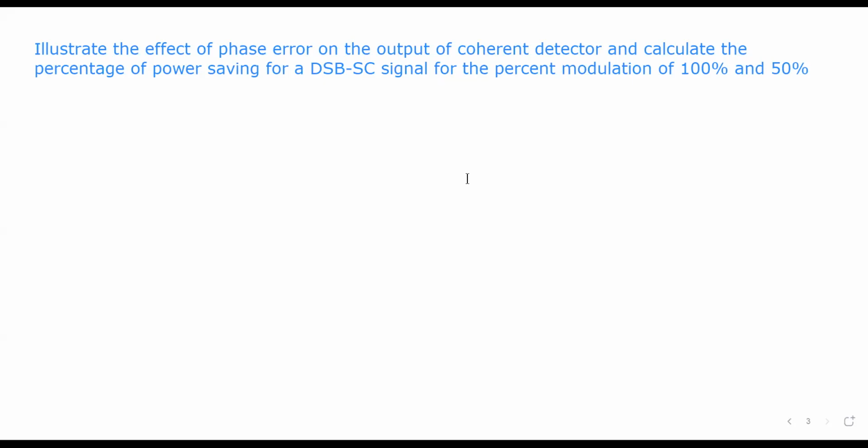So in the case of AM, double sideband full carrier, by using the expression for total power, PT equal to PC into 1 plus m squared by 2, and for 100% modulation we have taken m equal to 1, there we have seen that PT equal to 1.5 PC.